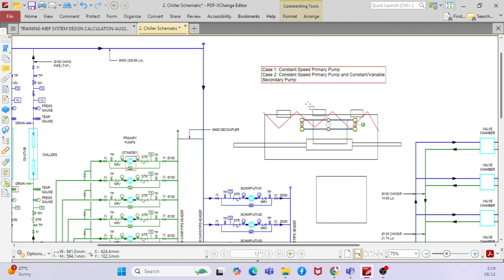So basically, typically 1500 is what manufacturers have on the shelf or is commonly used, and anything more than 1500 is more like custom built? It's not custom build, basically, but yes, you can say custom build also. You can request a higher capacity, but the length of the chiller will be very high, and you have to see whether the architectural layout can accommodate it or not.